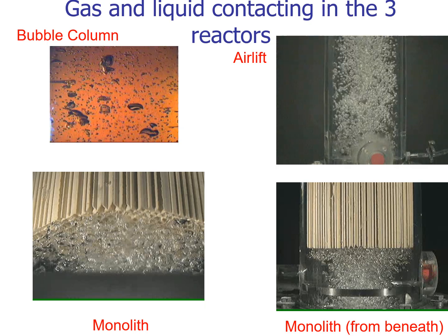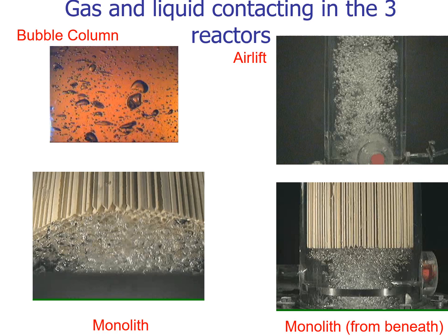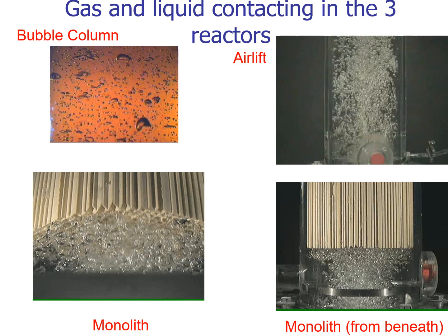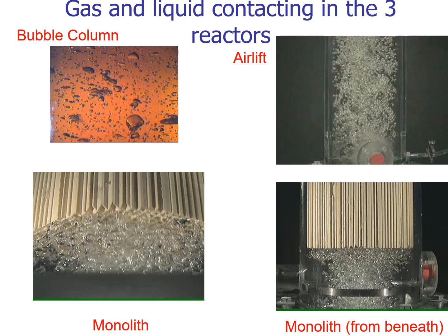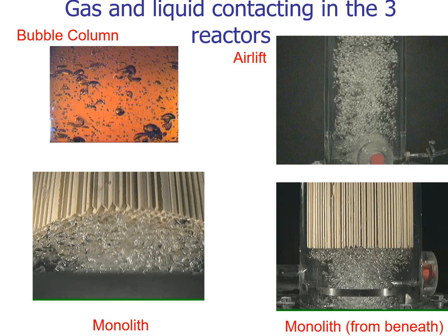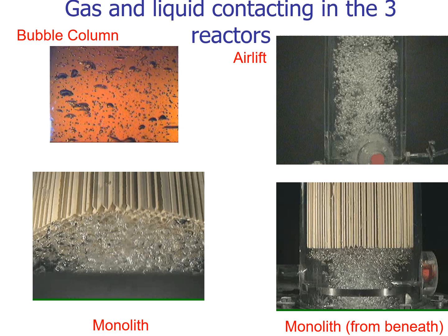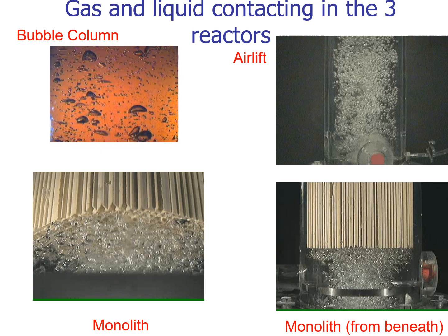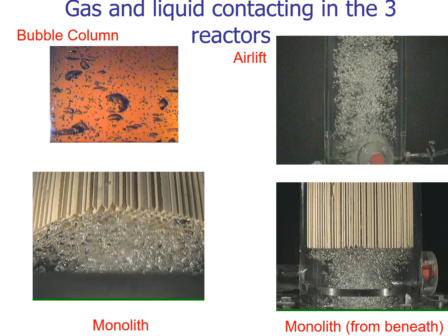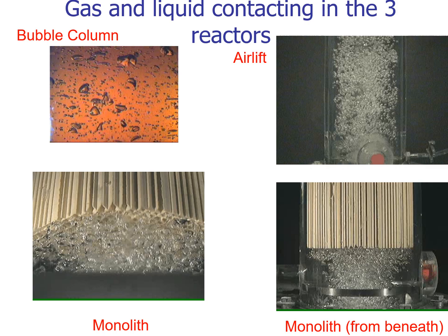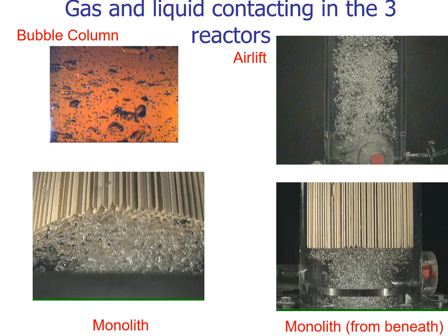It's like an airlift. We have, due to co-current flow of gas and liquid, the bubble sizes are more uniform, and on average, they are significantly smaller than that in a bubble column that does not have co-current upflow of the liquid phase in normal operations.